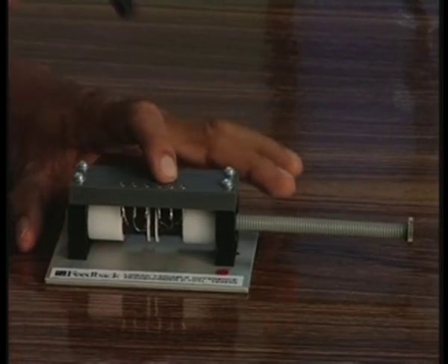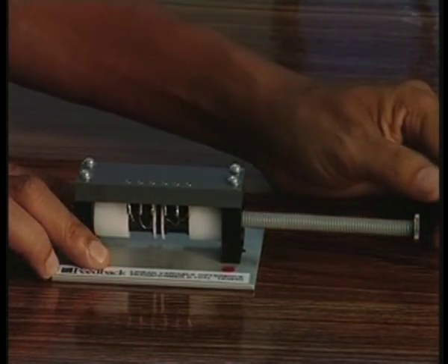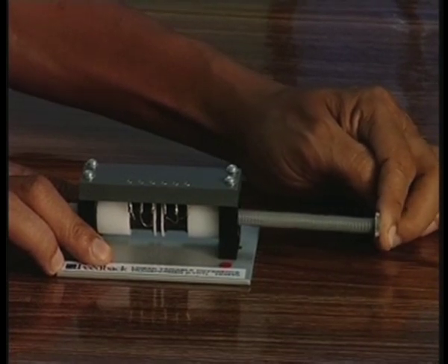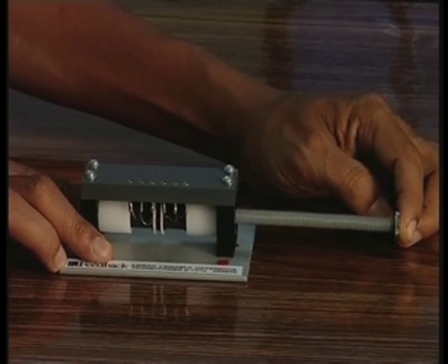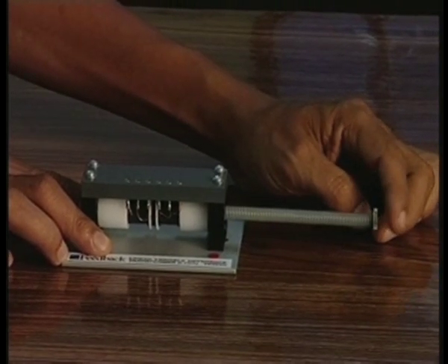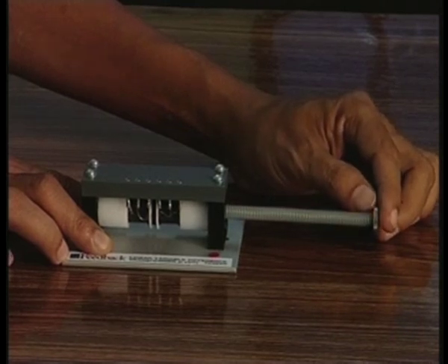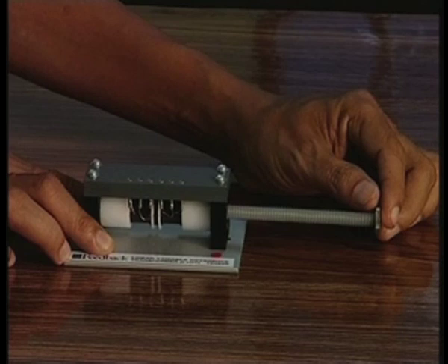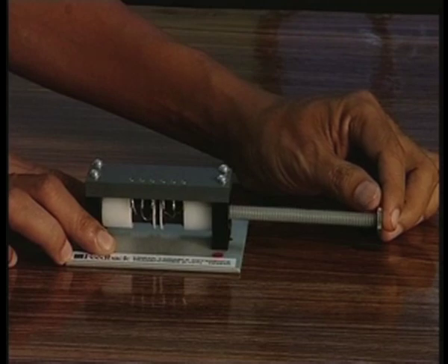You see here the core, a soft iron core, which will move like this. Now I am moving it, it will move like this. Since there are two secondaries in opposition, when the core is exactly at the null position, the two secondary output voltages will be nullified and I will get 0 voltage. But any position other than that will give you a non-zero output voltage. So, this is actually a pictorial view of the LVDT.